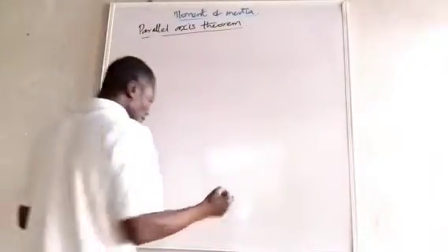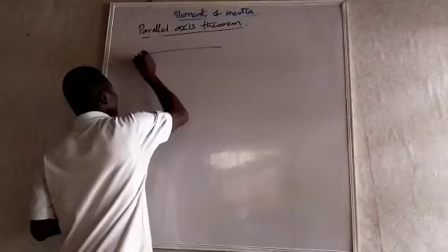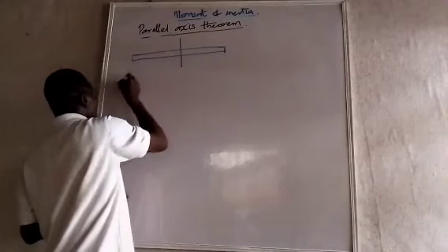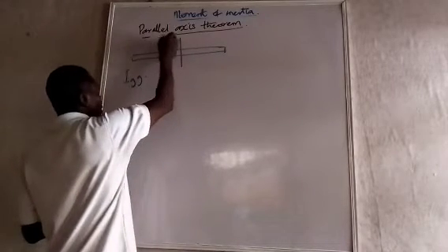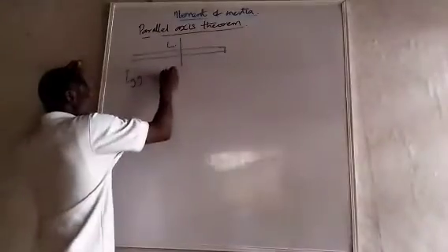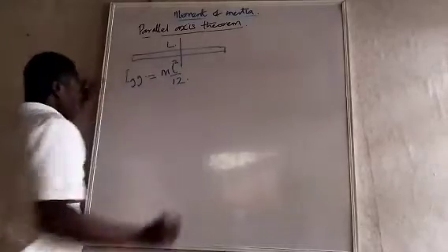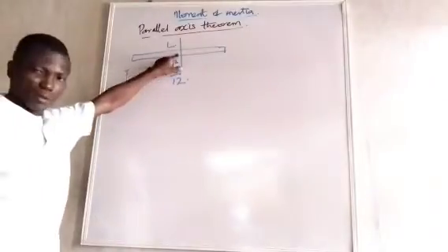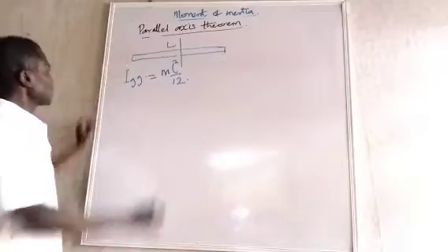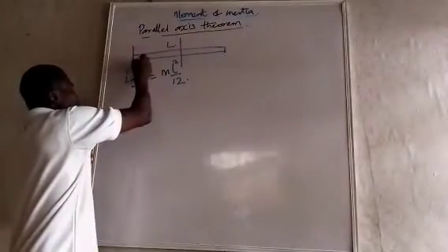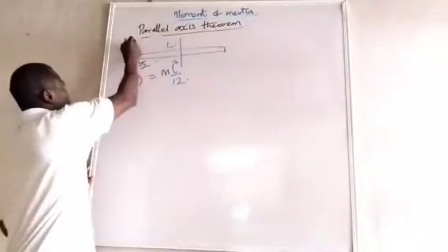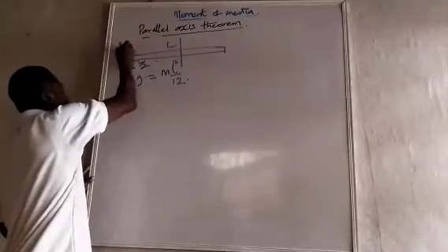Now you remember the example we just wrote. For this one about the CG, I G for the rod with length L, we said it was going to be M L squared over 12. Now, if we know that, and we want to find it about a distance of L over 2 from the center of gravity, what do we do? Let's say this is y.